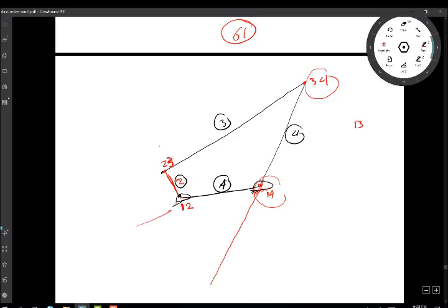And at the other end, I know this is 1, 2 and 2, 3. Common number is 2. The missing point is 1, 3. So I extend this other link here, and this will give me 1, 3. All right, okay. So at this point, why I'm doing that, this is the question.